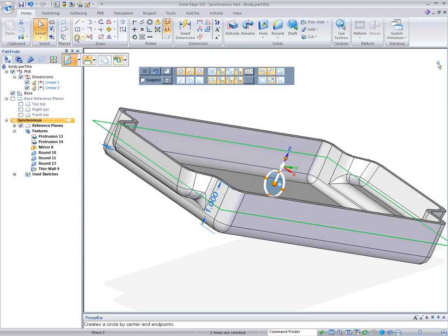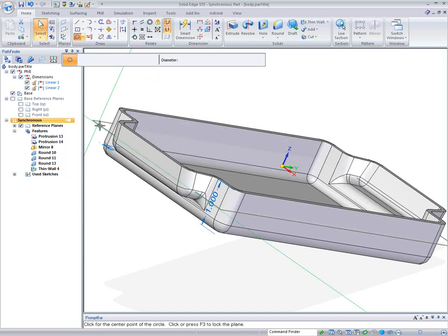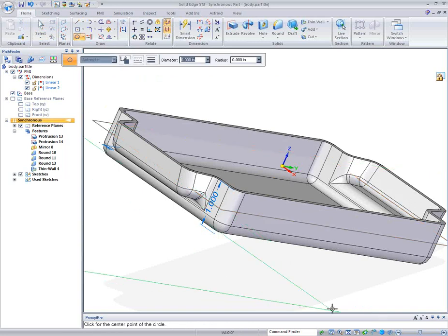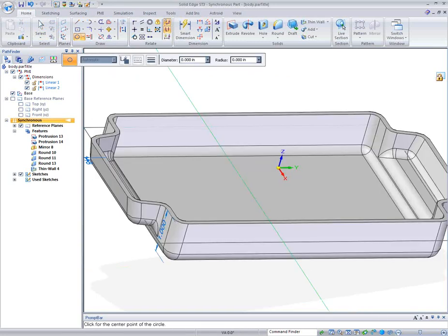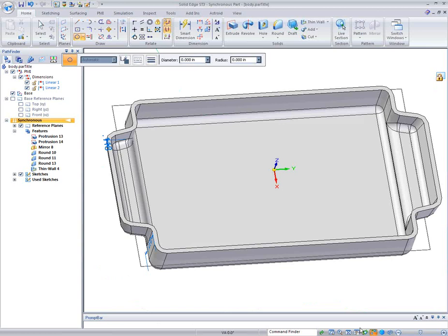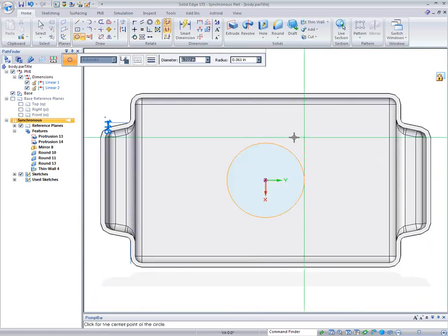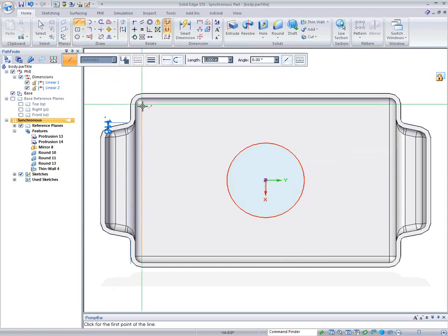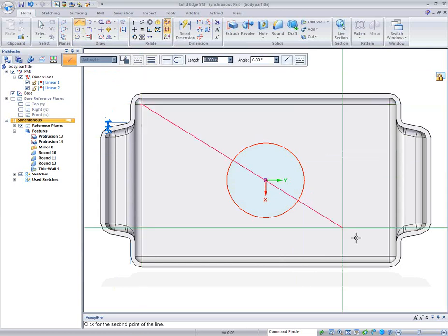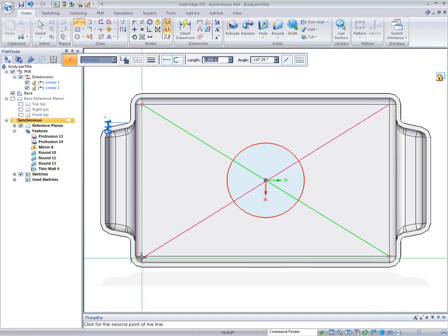Now, on that parallel plane that is sitting out there, I'm going to throw some geometry out on this face. So we'll put a circle out there, and then we'll switch over and do some lines. I'm just going to touch this over here, pick the center, go to center, center, to center right there, and then trim off some of the things I don't need.